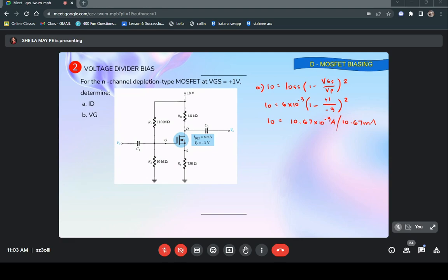So we have 9 volts squared, right? 6 minus 3 is 3. Squared is 9. So you cancel V squared here. So ang mahabilin, ID is just 0.24 times 10 to the negative 3 times 9. So that's 2.16 milliamperes. Oops, milli na siya. So we have already solved our ID.